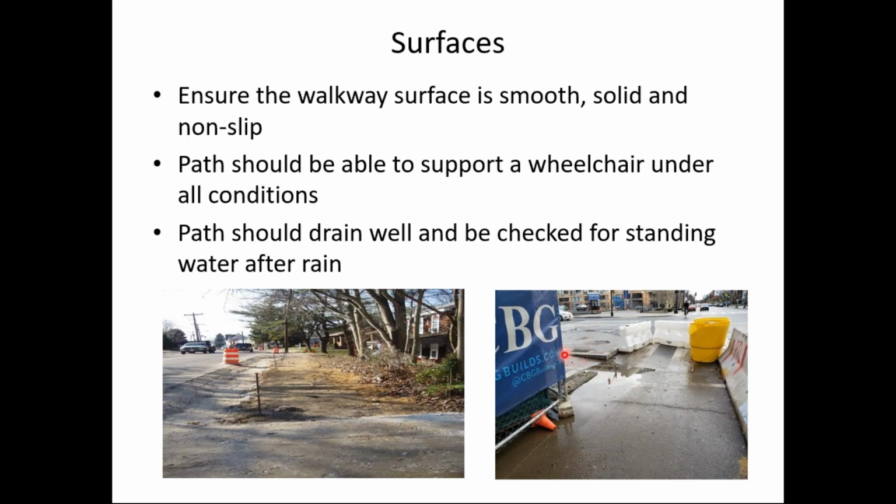This was an existing curb ramp. Actually, it's not compliant with PROWAG because this is all sidewalk, and so it needs to have flared sides, not vertical curb return sides. But anyway, the key thing I want to point out is notice there's a big drainage issue here, a lot of standing water. That's just kind of a nuisance to all pedestrians, especially if you're in a wheelchair. The wheelchair wheels throw up the water onto your coat or clothing or whatever.